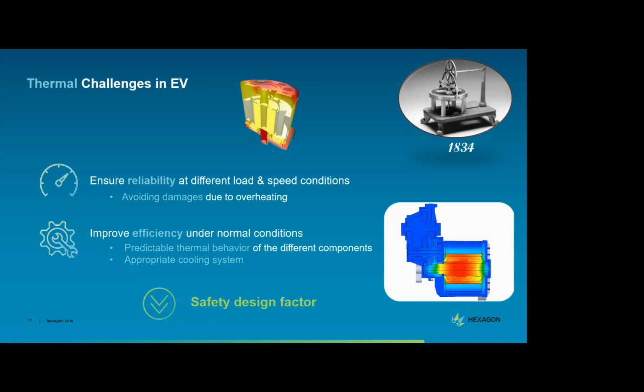So what we want, in the end, is to avoid overheating, as it could lead to breakdown of the stator winding insulation or demagnetization of the magnets. In addition to these above-mentioned issues, we obviously want to improve efficiency under normal conditions. That means we need the most predictable thermal behavior of the components to finally design the most appropriate cooling system. We can easily understand that thermal management is critical to improve electric machine performance and ensure reliability.